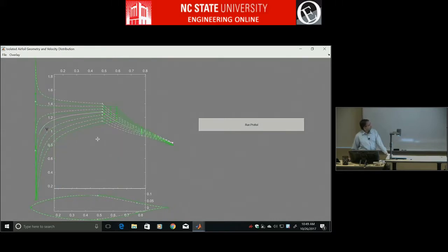And then in the velocity distribution, earlier you had a favorable gradient at alpha equals 2 or something. Well, it's changed a little bit now. Yeah, I think that's correct. At alpha equals 2, it was a favorable gradient, and then became suddenly adverse. Now you've got 2 more segments. Really the problem hasn't gone away because it's become favorable to a longer distance, and then there's a sudden adverse gradient. So what you have to do is somehow make these things more adverse, right?